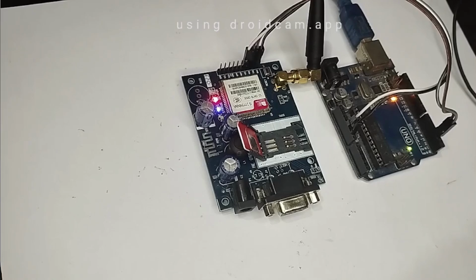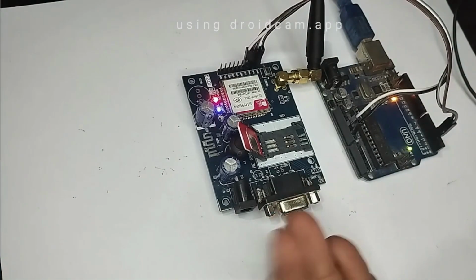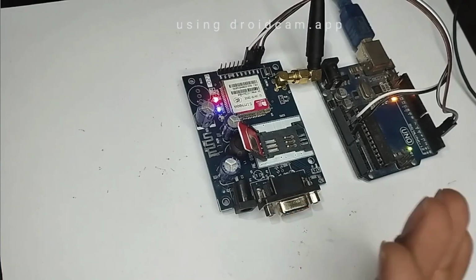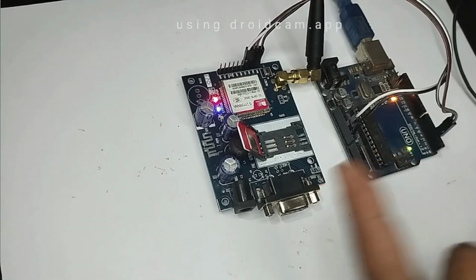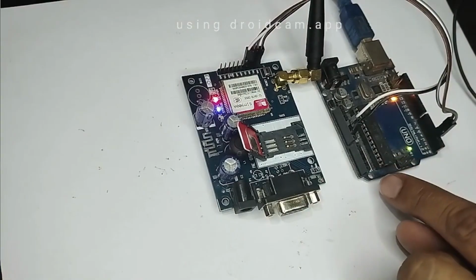So for that, if I use a single serial terminal, it could be RealTerm, Tera Term, or PuTTY. Whatever message I type, it will transfer from the computer to this Arduino, and Arduino will simply forward that message as it is to this GSM module. Same way, if the GSM module types OK in response, the Arduino will simply forward that OK to the PC. So it's just an intermediate device.